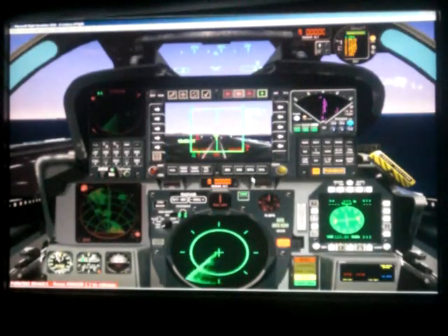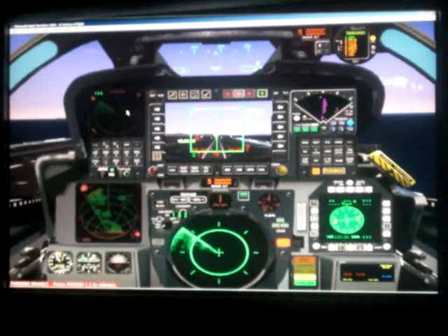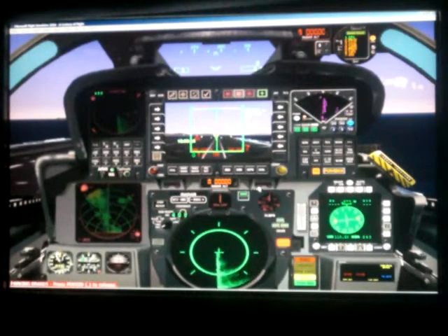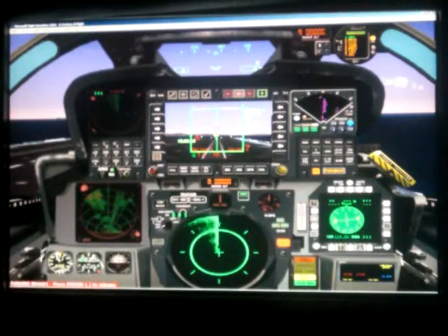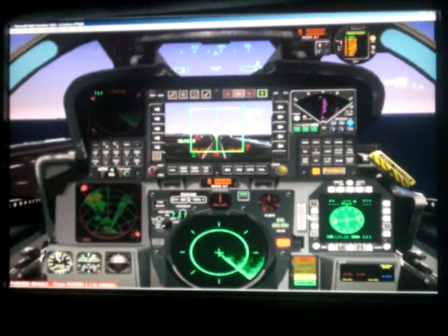And then lastly, a meatball gauge, so that you can actually land the plane from the rear seat if you'd like. This is a radar. Unfortunately, it's just kind of a dummy radar. Same thing with this dummy weather radar, but I figured I'd throw them in here just to make the Rio seat look more realistic and cool and functional. It's got left and right fire emergency alarms. Your nav GPS switch here is in the back. Another radar, your flaps gauge, gear, etc., and then lower left, standby airspeed indicator, your altimeter, and attitude.